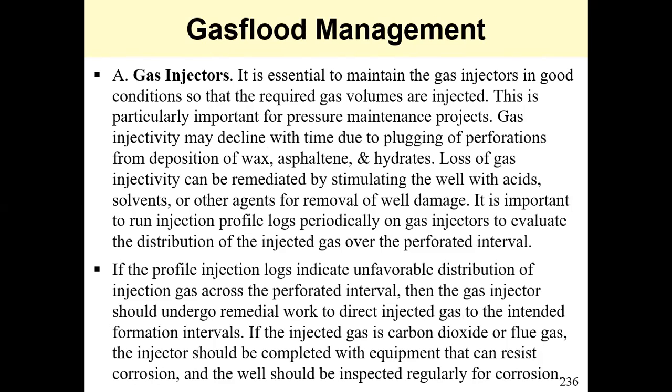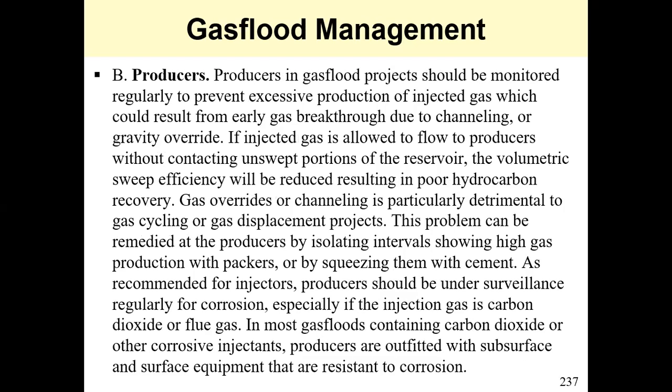If the injection profile logs indicate unfavorable distribution of injected gas across the interval, then some remedial work will need to be done. If injected gas is carbon dioxide or flue gas, the injector should be completed with equipment that resists corrosion. And of course, you need to still inspect from time to time.